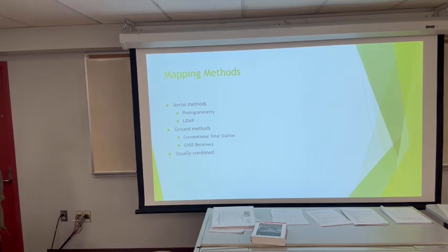Likewise, some other ground methods would be shooting some random or intermediate points around. Photo identifiable points is a common name used, where the photogrammetry and the LiDAR can use those for ground truthing, meaning they can use them as a check shot, verifying how good the LiDAR data is compared to the ground data. It's kind of a check for accuracy.